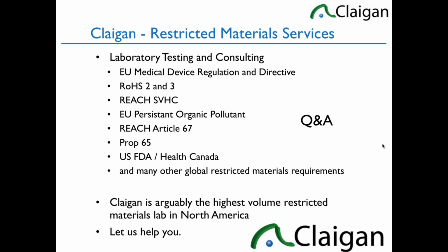Why did you put RoHS under electronics? Isn't RoHS now required for all parts of the medical device? Great question. RoHS only applies to electrical and electronic equipment, so it only applies to medical devices that have an electronic function. That doesn't include purely optical; it has to have an electronic function. If a medical device does not have an electronic function, then RoHS doesn't apply to it. The cadmium restriction is also a REACH restriction, so some of the restrictions appear elsewhere even if it's not in scope of RoHS, but RoHS only applies to medical devices that have an electronic function.